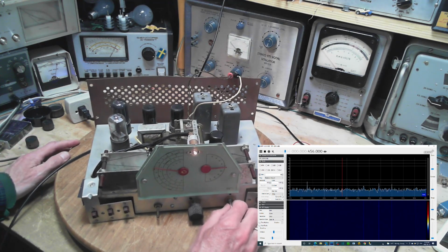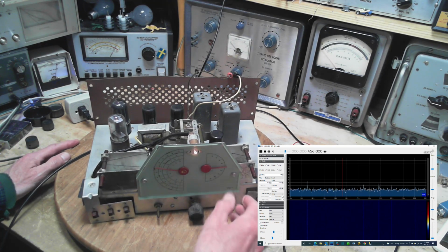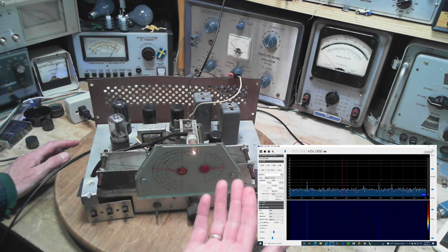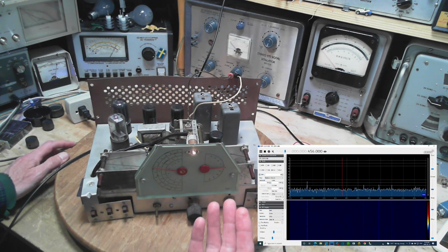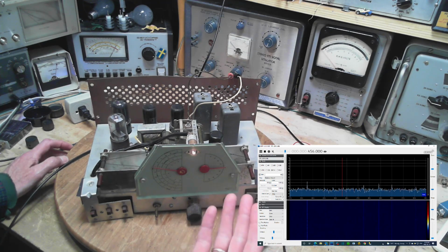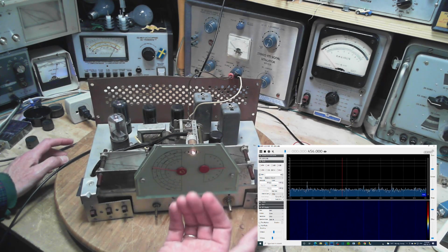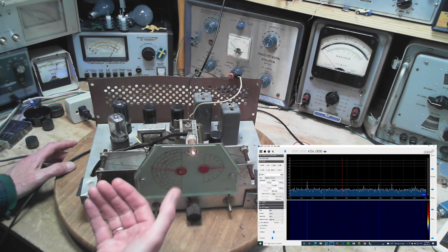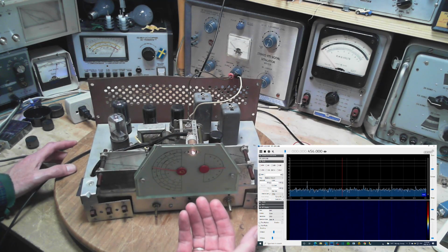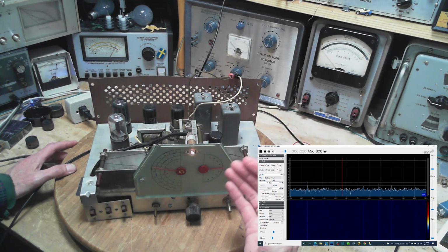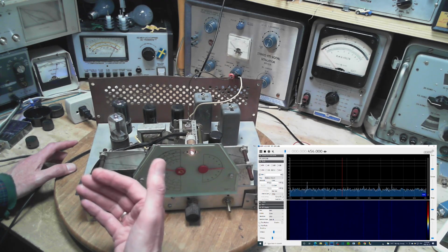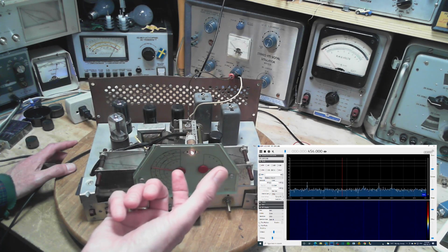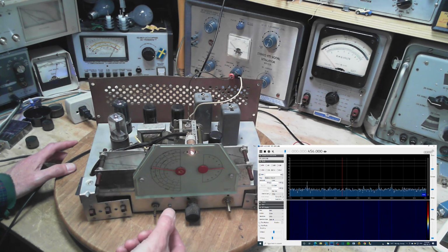So a couple things may have happened here. There may be a very strong signal coming in from the antenna now, much stronger than the 455, let's say. That's going through the radio as it should, even if it's just noise. It's still being converted and going through the radio. And the extra signal is causing the AVC to quiet down the radio.